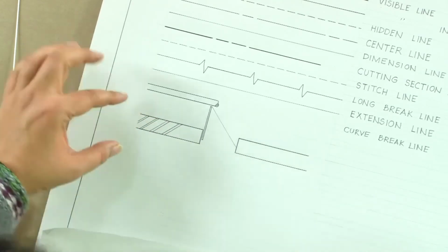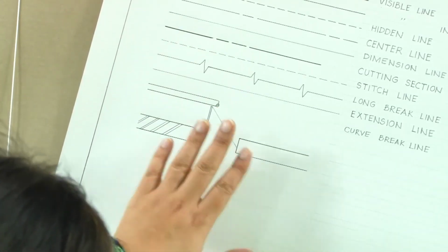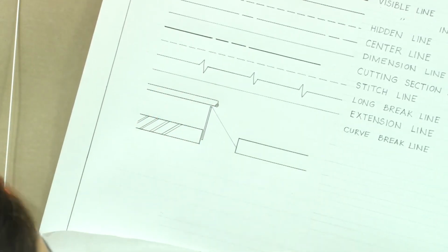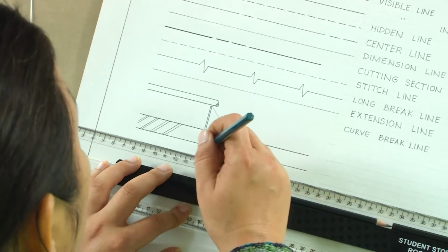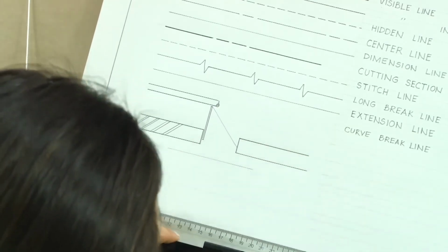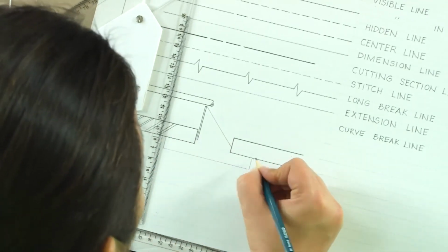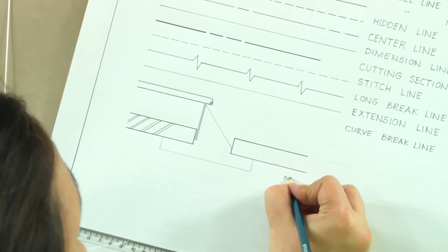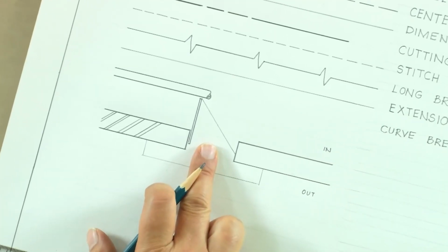Now if this single door does not have any step towards the inside or outside, it implies that this is an indoor door, placed inside the building. In case we want to mention that there is a step outside, we will make a line in the elevation which will be representing the step, not a staircase but just a single step. So this automatically represents that this is the outside and this is the inside. This is the representation of a single door.